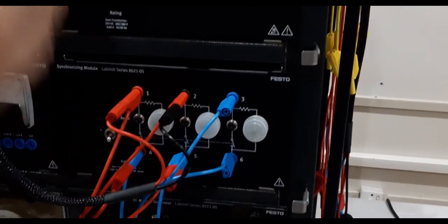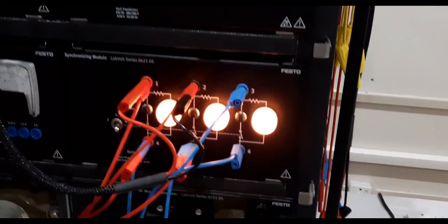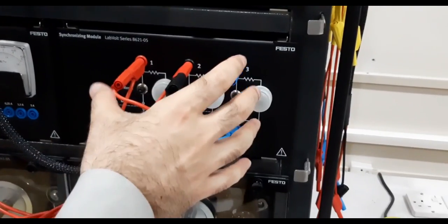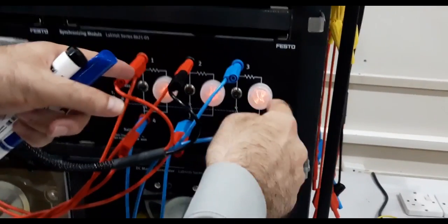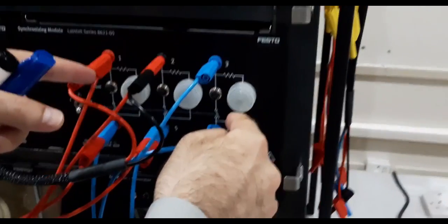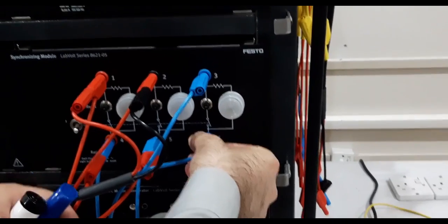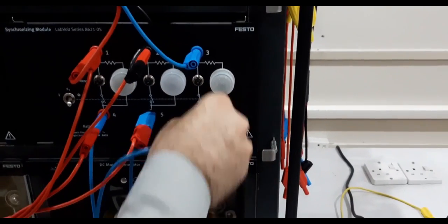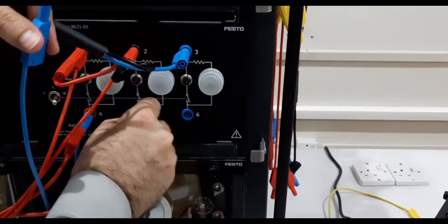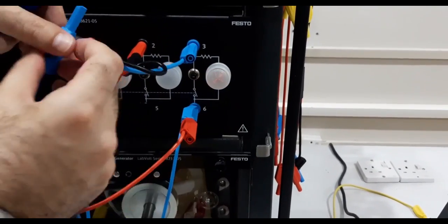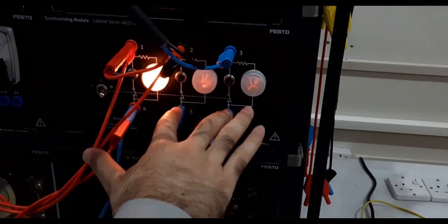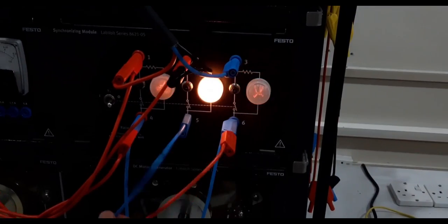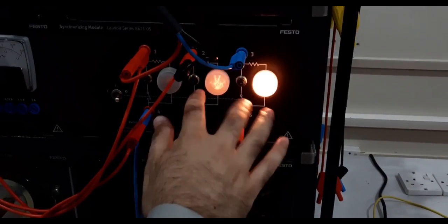So we discussed that 4 conditions need to be fulfilled. The 4 conditions also include the phase sequence. So let me change the phase. You see, there is no blinking. Okay, so if I change the phase sequence, let's say, you see here, if I change the phase sequence, one can still see the blinking of the lamps. I just changed the 2 connections of the machine, and one can see now the blinking of those lamps.